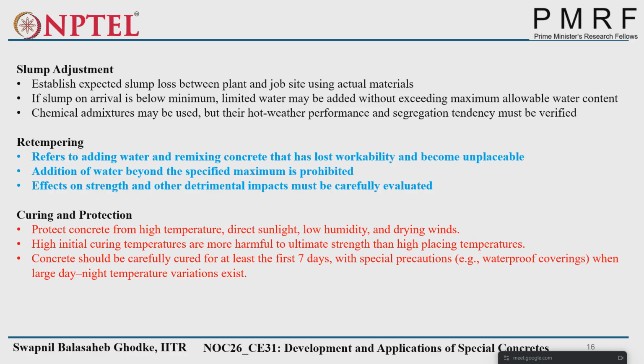Curing and protection. Protect concrete from high temperature, direct sunlight, low humidity, and drying winds. High initial curing temperatures are more harmful to ultimate strength than high placing temperatures. See carefully, see the sentence.